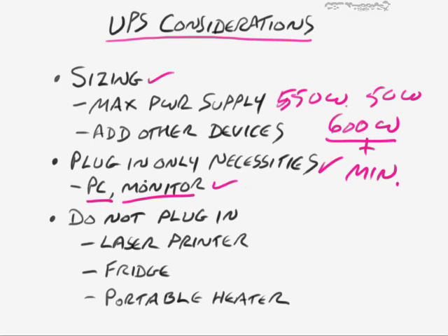But you do not want to plug in additional items that you don't really need right now, such as the laser printer especially. Laser printers are very electrically noisy, and if someone sends a print job through it, it'll pull a huge amount of power off of that UPS. So you don't want that. Now, if you absolutely had to, for whatever reason, plug in some kind of printer, you could possibly plug in an inkjet printer, because they don't draw as much power and they're not as electrically noisy as a laser, but I would still advise against that as well. You just really don't normally need it.